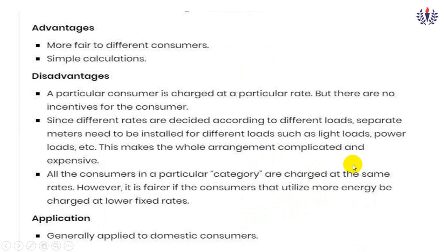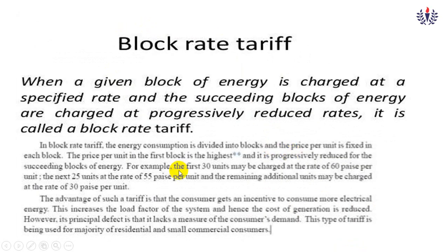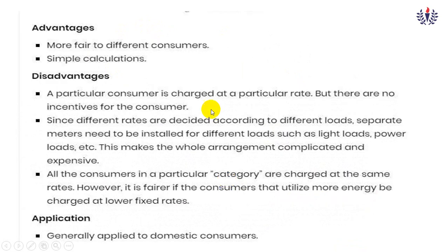So what are the advantages of the flat rate tariff? Sorry. So here it's more fair to different consumers and the calculation is simple. As we told, one group of consumers will have one value. But here, some drawbacks are also there. A particular consumer is charged at a particular rate, but there is no incentive for the consumer. So that is a big drawback.